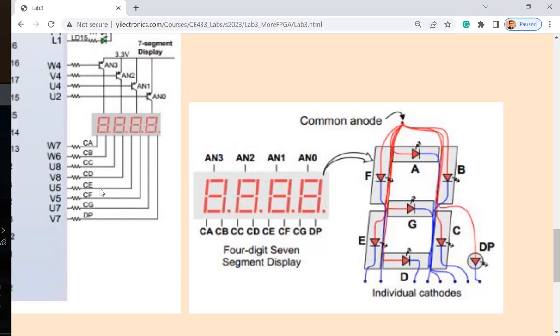So how do you select it? How do you turn on here? You need a high voltage to turn it on. So you need the transistor to be on. So you need the channel to be on so you can short this high voltage to here. You can turn on individual ones.